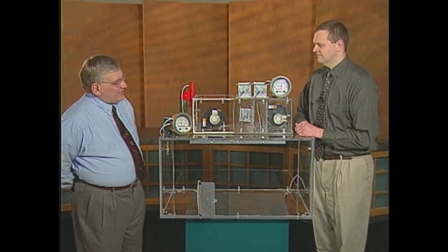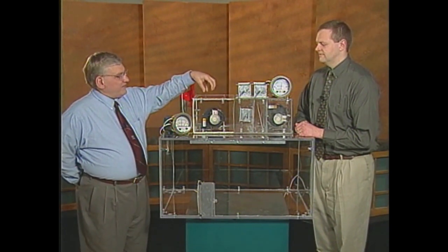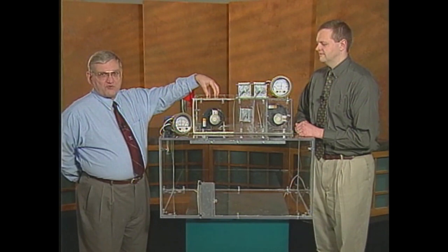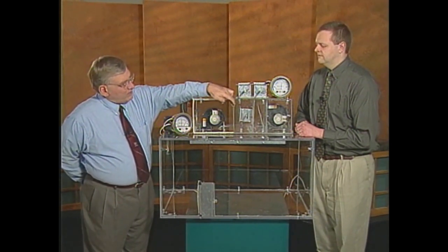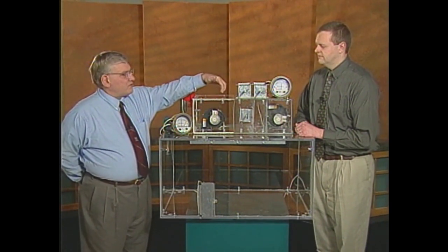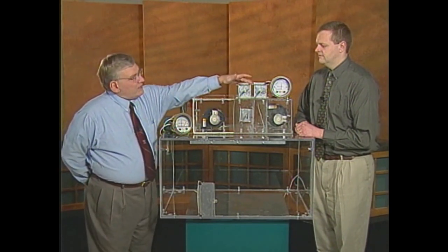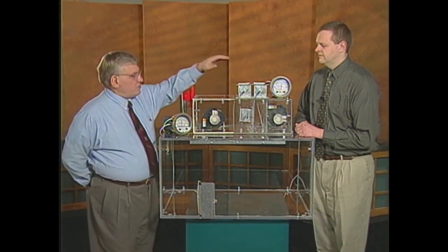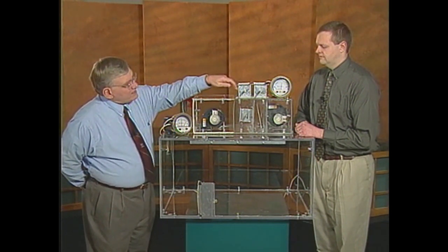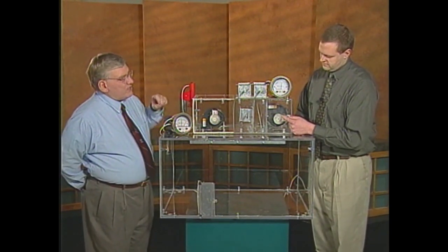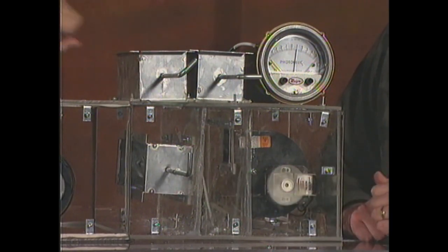This is a return fan unit again. Let me walk through briefly the 4 control loops for you. Being a VAV system, the VAV supply fan is controlled by the duct static pressure. The outside air and the return air dampers are controlled by a mixed air thermostat in the mixed air chamber. The relief damper is used in controlling space static pressure. And the final one is the return fan CFM, which is being controlled by the pressure in the return air plenum.